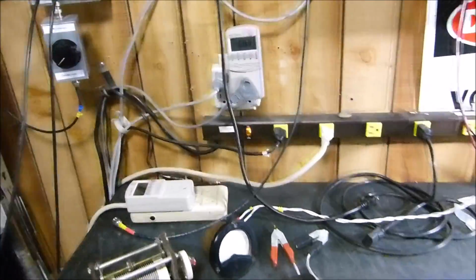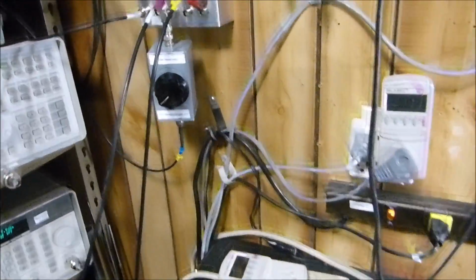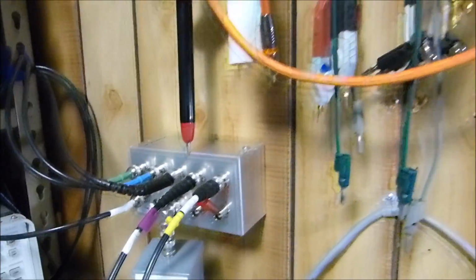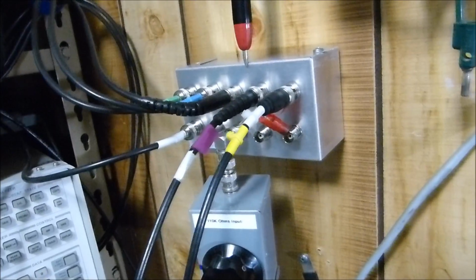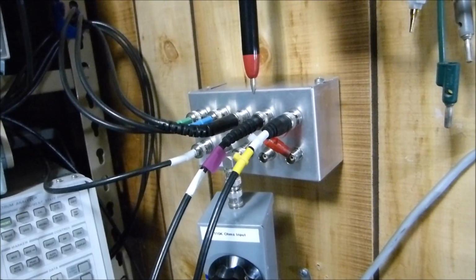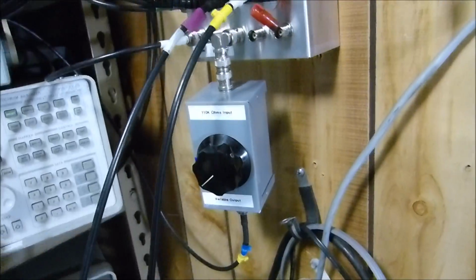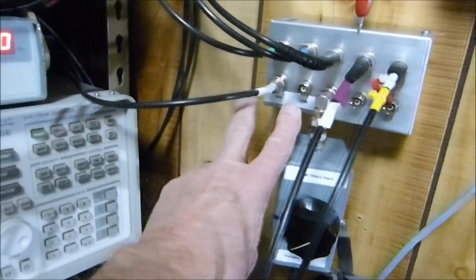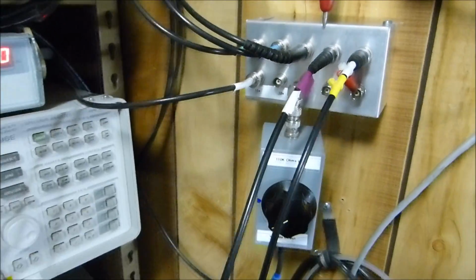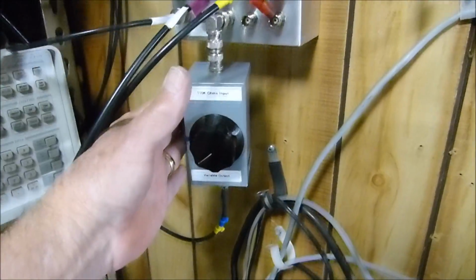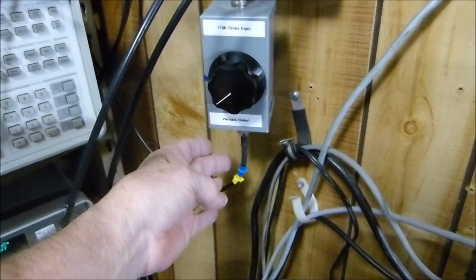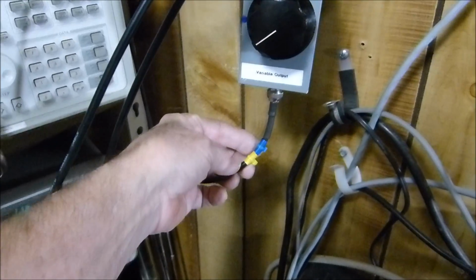And like I say, the things that I like to see are how you guys set up whatever you use. This little breakout box is coming in really handy, and I know there's been a number of discussions about it, and other people have built similar devices. This one is a variable one. I do have 2 attenuated ports over here, and they are compensated, just like an oscilloscope probe. You have to do that. This is not compensated, so you wouldn't actually want to take the output of this and put it into a spectrum analyzer.